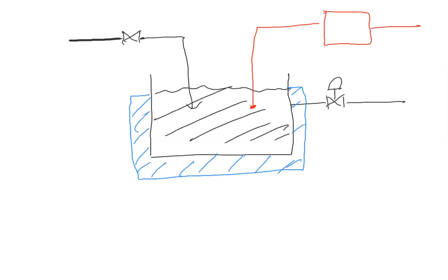This is the control diagram. That's a GC. This is the measurement. This is operating the valve. Now, if you try to understand the measurement, where is it sitting in the plant? What is this signal? This is nothing but a data cable which is carrying a current of, let's say, 4 to 20 milliamperes. How do you calibrate this 4 to 20 milliamperes? Let's say the temperature of the CSTR. What is the minimum temperature that it can get? It is 40 degrees, because the feed temperature is 40, no?